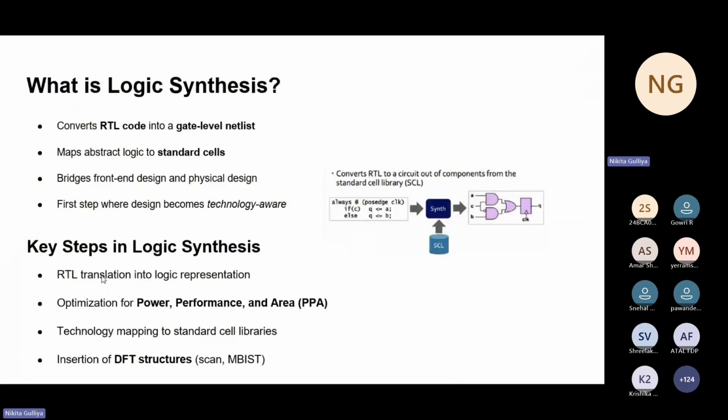And what is logic synthesis? Logic synthesis converts the RTL code into a gate level netlist. It maps abstract logic into standard cells from a technology library. This is the first stage where the design becomes technology aware. Synthesis also optimizes the design for power, performance, and area, and may insert DFT structures also.